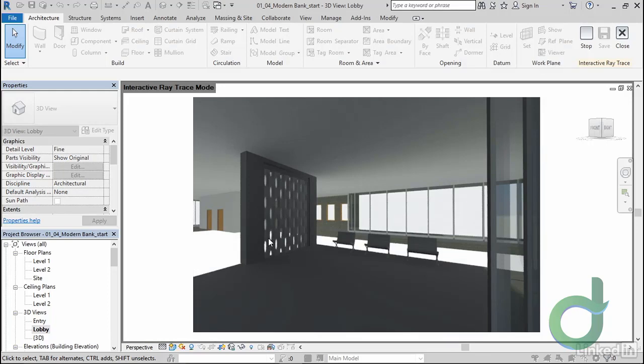What I'll often do is test out my round objects to make sure that they look, well, nice and round in a render before I export them across. This way, if there's anything I need to fix in a family and then have those changes propagate through many objects, it's better to do in Revit than it is to try to touch it up later, even though things may come in as an instance. What I'm going to do is to move that camera closer.